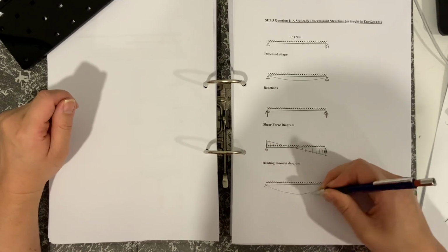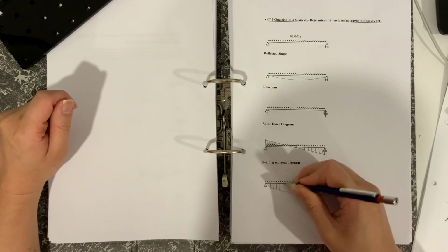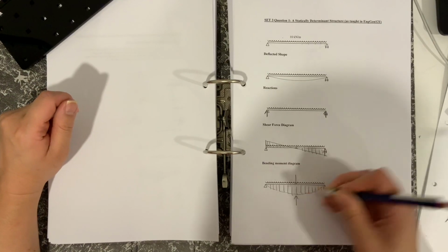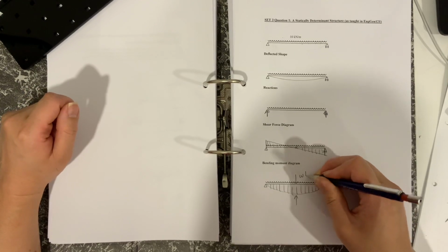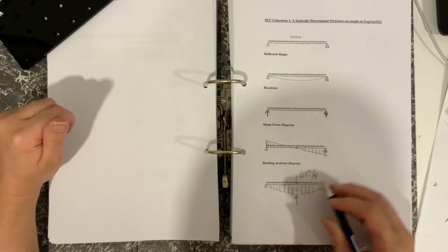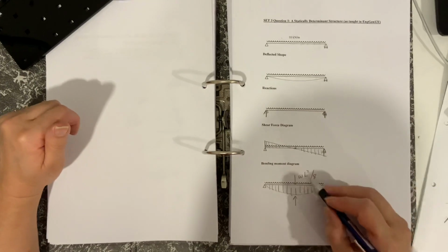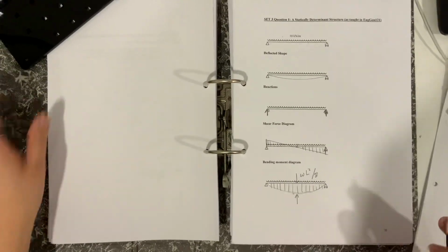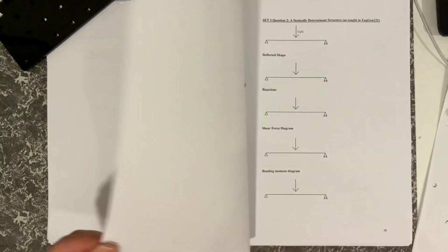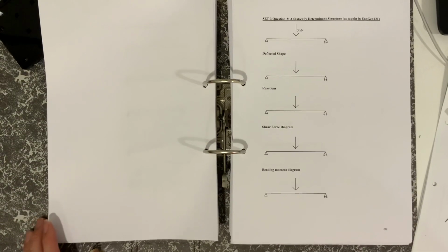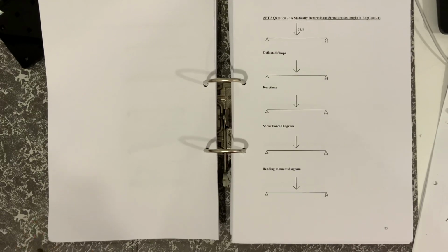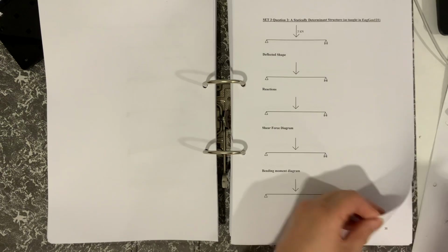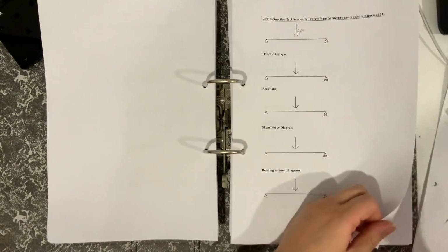So there's very little that you need to remember, but we remember PL/4, and we remember that the bending moment there is WL²/8, where W is the load, L is the length of the beam, and the number 8. And you can derive that, of course, as we've done in the previous examples. So let's look at the next one. So this one we've done before, simply supported beam. And this leads on to set 3.